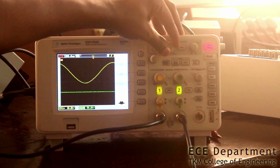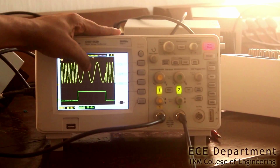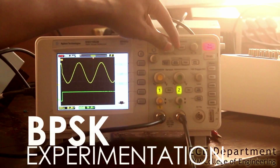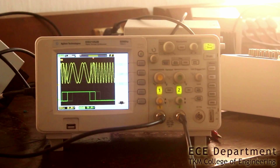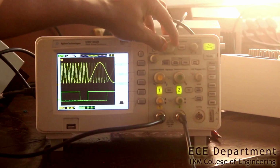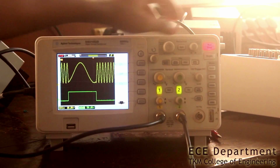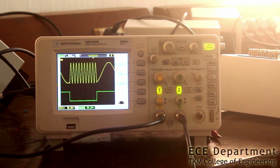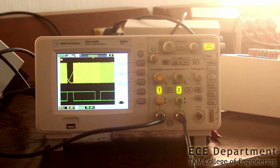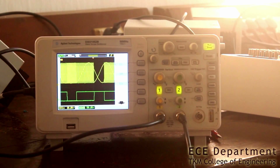We have now successfully implemented a BFSK modulating circuit. Like we discussed earlier, in BFSK modulation, the frequency of the carrier signal is varied in accordance with the amplitude of the modulating signal. In our experiment, the shift in frequency has been achieved by using a switching mechanism. By feeding carrier signals of different frequencies to two different switches, we have managed to successfully implement the BFSK modulation scheme.